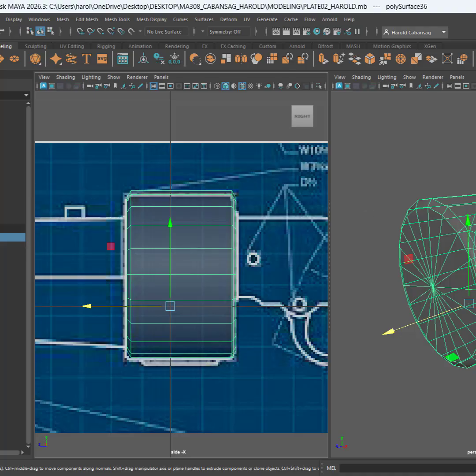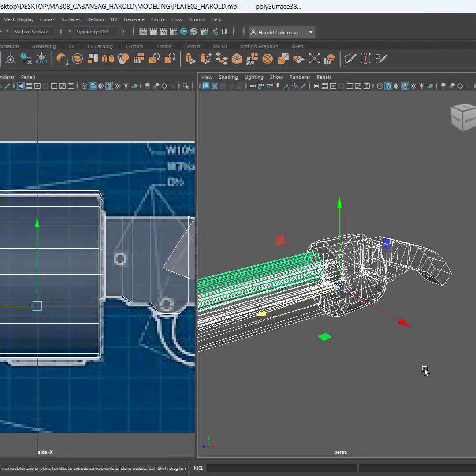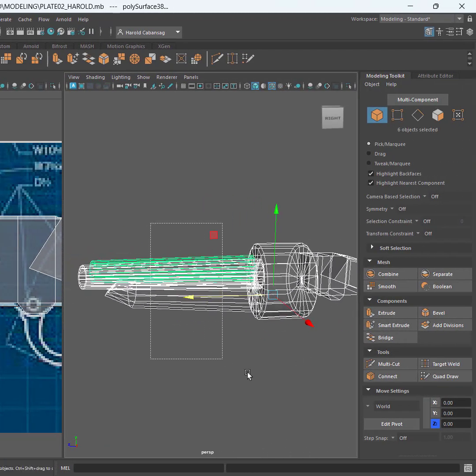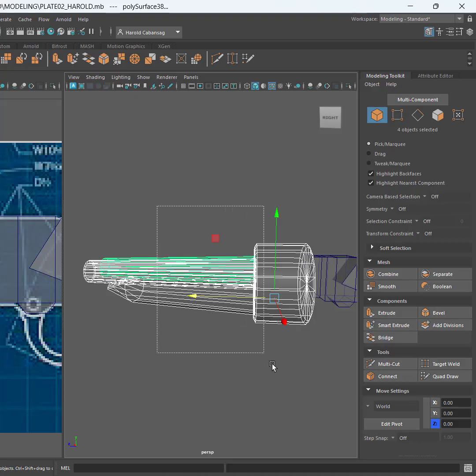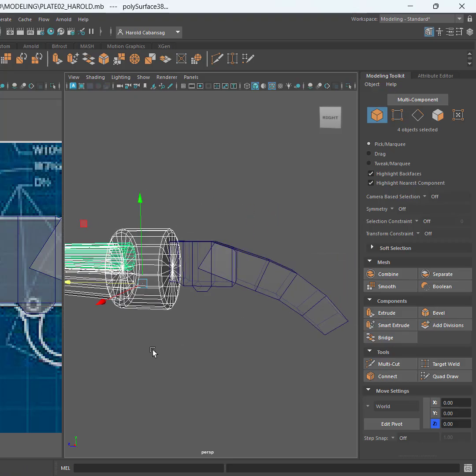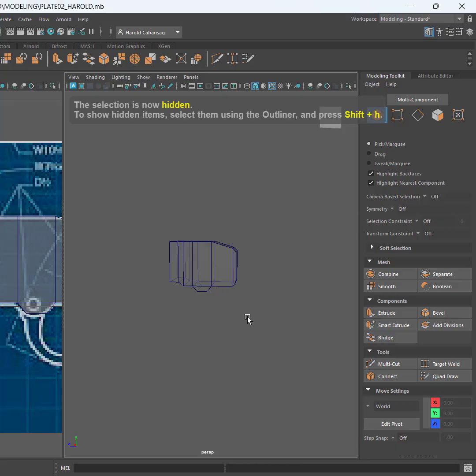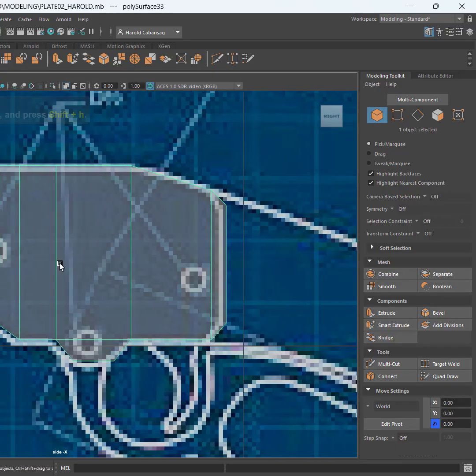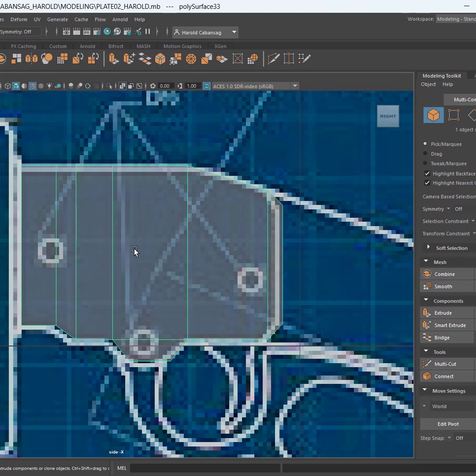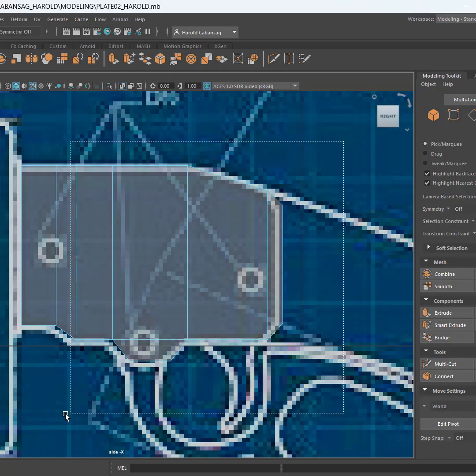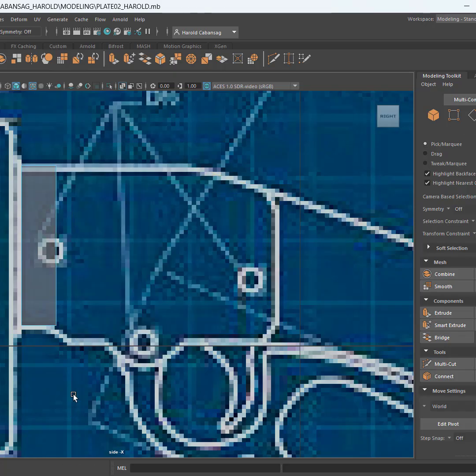Okay, so checking in again, Shift H. So I have deblocked these parts. So now I'll just hold Control, hold Shift and select, and Control H to hide. So we'll talk about this part. This part was achieved just by a series of extrusions. Let me just repeat it to you. I'll just show it this way. I'll delete this, for example.